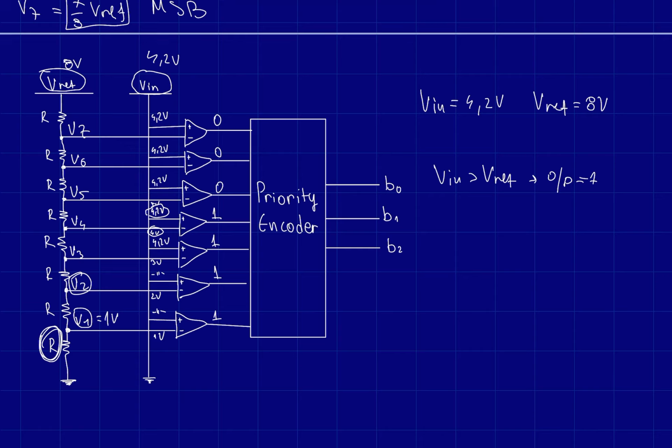As you can see here on the right, I wrote a priority encoder, which means that the flash ADC will give some of the outputs a priority and will choose just one of them, since we want to convert just one voltage. In the flash ADC, it will always choose the highest one, which in this case is the one right here.